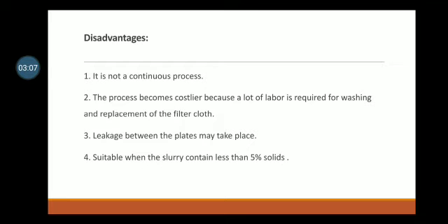Disadvantages: it is not a continuous process. The process becomes costlier because a lot of labor is required for washing and replacement of the filter cloth. Leakage between the plates may take place. Suitable when the slurry contains less than 5% solids.